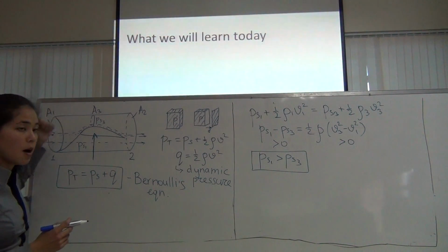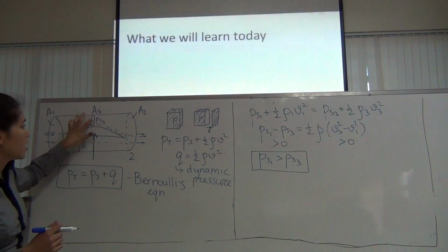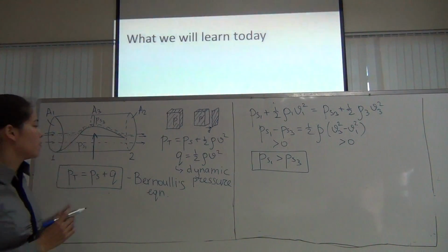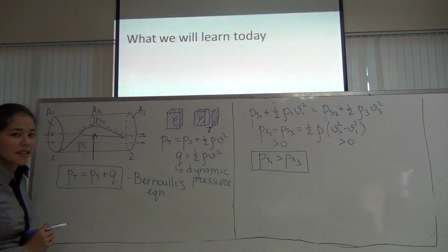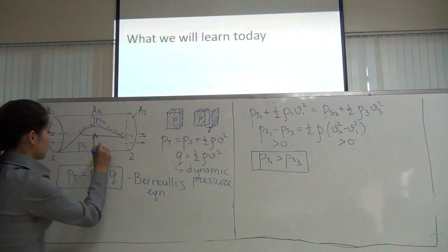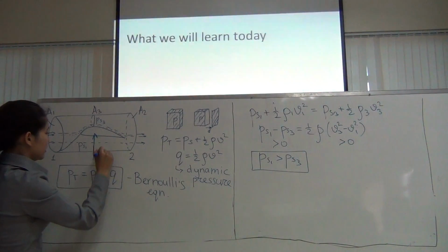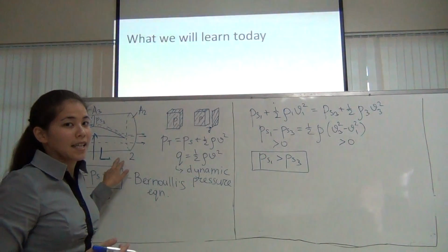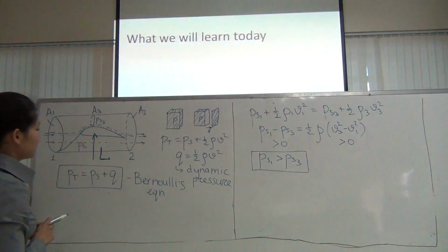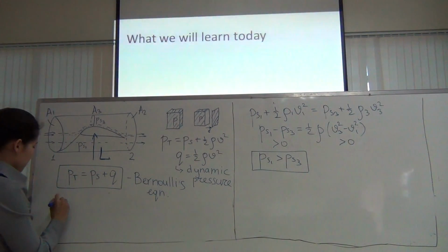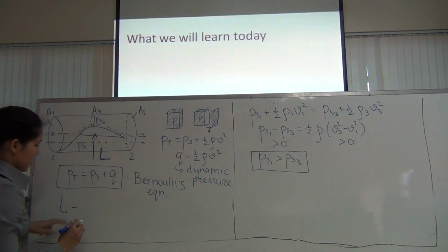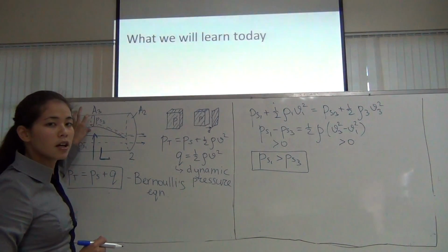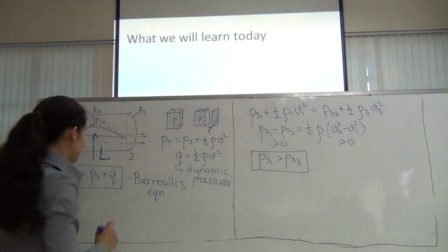In this case, it will be upwards, since velocity of air above the airfoil is greater than the velocity of air below the airfoil. And what is this force? So this is our famous lift force. It is denoted as L. And this is why airfoil and wing and aircraft is able to fly. So let's write down that lift is an aerodynamic force that results from pressure distribution on the surface of airfoil.